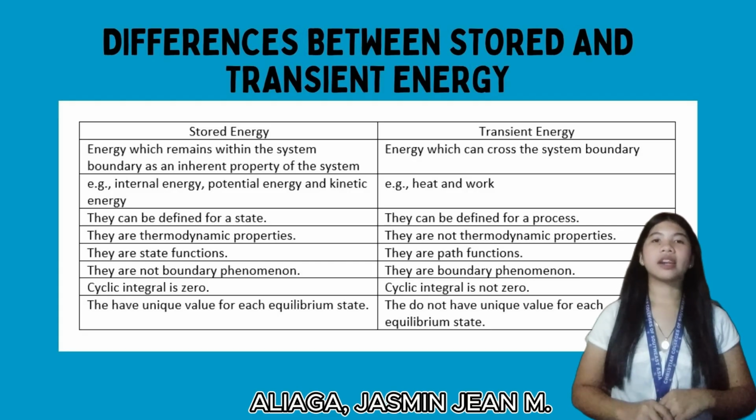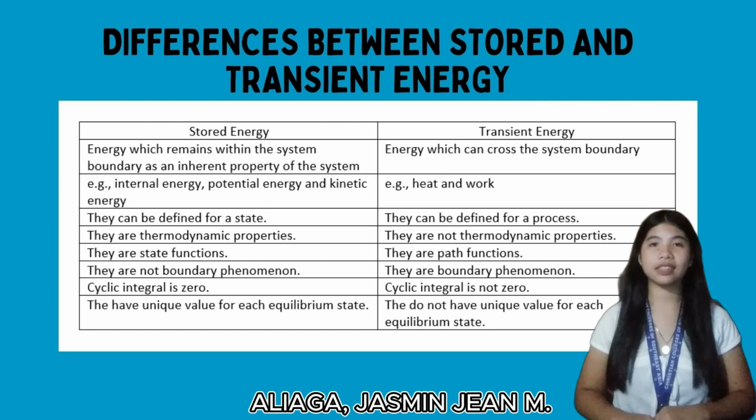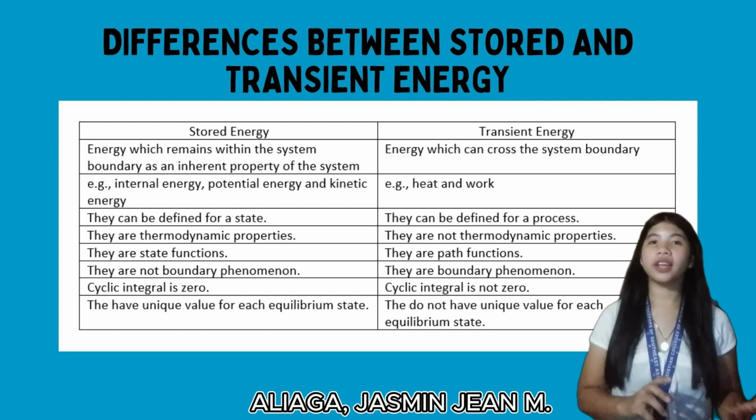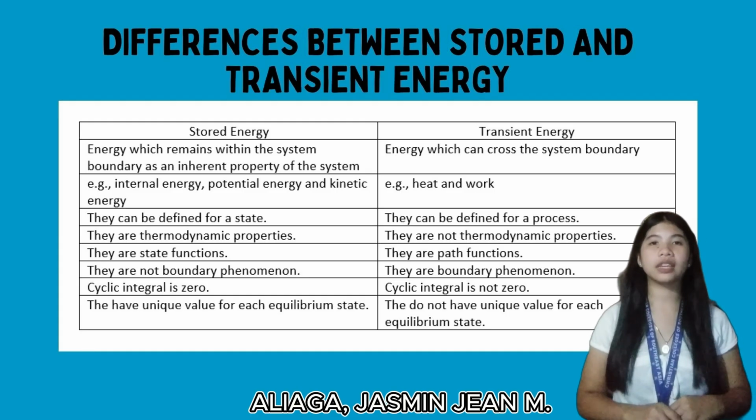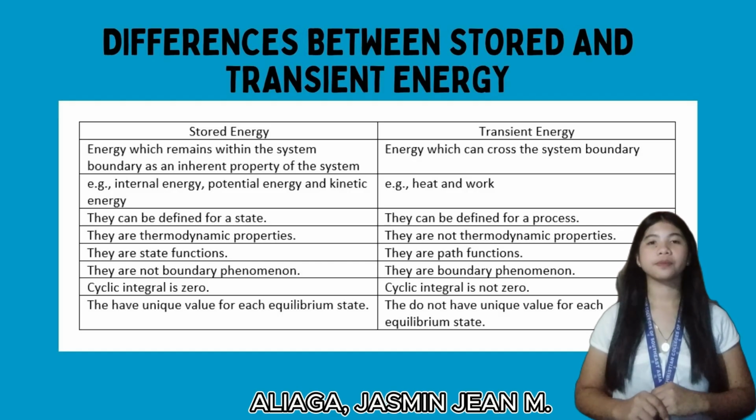For stored energy the cyclic integral is zero, while for transient energy the cyclic integral is not zero. Stored energy has a unique value for each equilibrium state, while transient energy does not have a unique value for each equilibrium state.